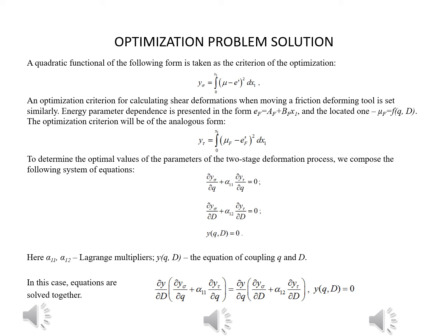For hardened high-manganese steel, when rubbing against granite with an interlayer of iron oxides, lambda is almost equal to delta and almost equal to 0.4. When rubbing against manganese, lambda is almost equal to delta, and both are almost equal to 0.7.